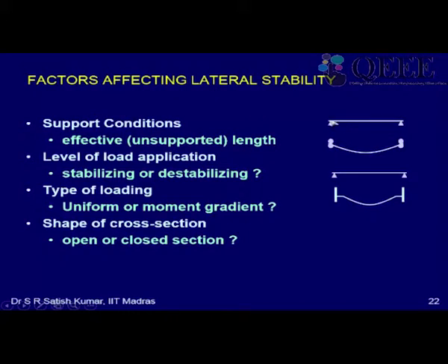So I've just shown here, this is the elevation of a simply supported beam. Of course I should have shown a roller here. So one hinge, one roller, and this is the plan of the simply supported beam. So it doesn't really matter what is the end condition in elevation. What matters for lateral buckling is what is the end condition in plan.